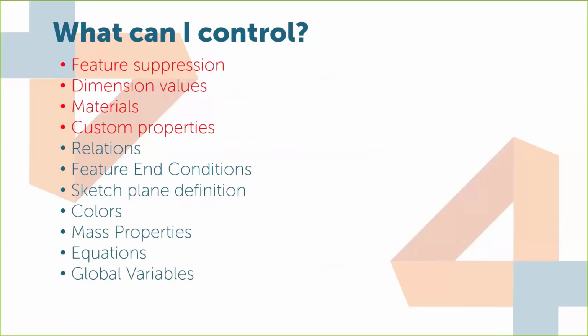Now, just from personal experience, I tend to maybe stay away from configuring my sketch relations. It is functional. You can suppress and unsuppress sketch relations. But I personally, just my opinion here, find it easier to control that behavior with two different sketches, for example, and then simply suppress and unsuppress those two sketches to get the behavior of different relations.